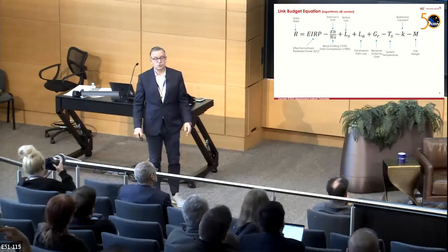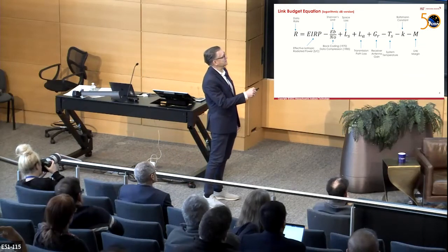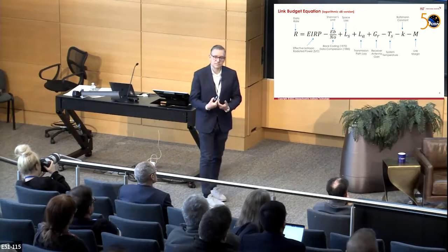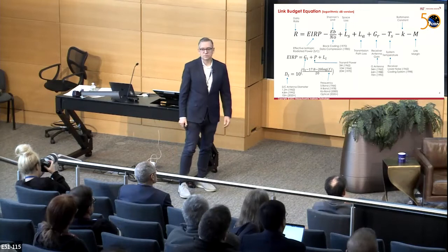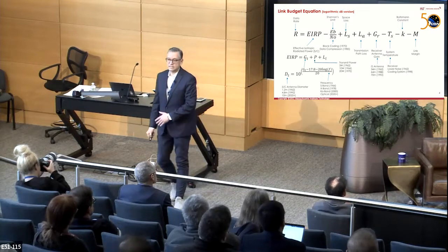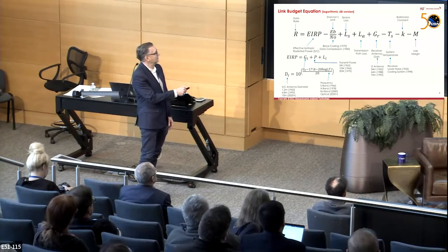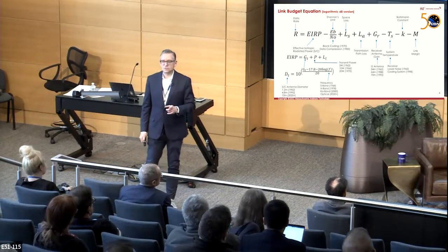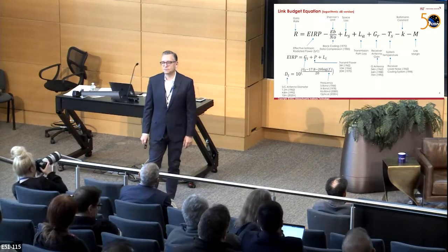The space loss, can't do anything about that. That's the distance from Jupiter. But some of these other factors we can do a lot about. Transmission losses, antenna gains, system temperature, keeping the receiver really cold. And we can break it down into the second level and third level of decomposition. So the radiated power depends on gain, the transmitter gain, the power in the signal, and so forth. And every one of these terms has improved and contributed to that 13 orders of magnitude.